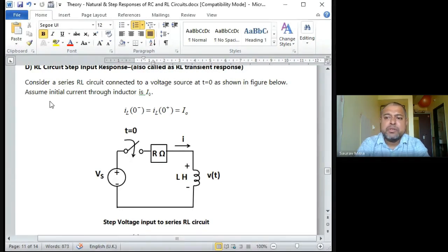We are sampling because we want to digitize it. So 100 hertz is the sinusoidal signal we want to digitize. Then 200 hertz should be the minimum sampling frequency you have to take. That means you can get only 2 samples in the total time period of 1 by 100 seconds, that is 0.01, which is 10 milliseconds. So 100 hertz means 10 milliseconds. 0.01 multiplied by 1000 gives 10 milliseconds.